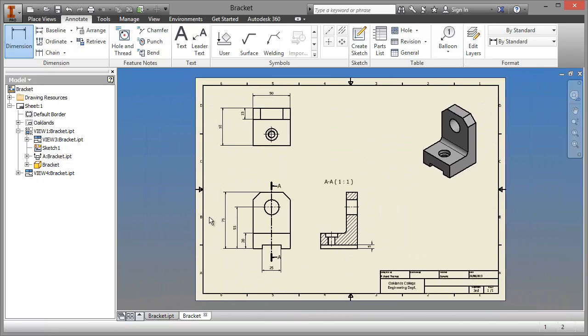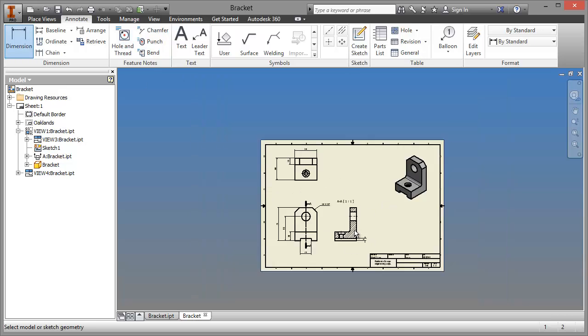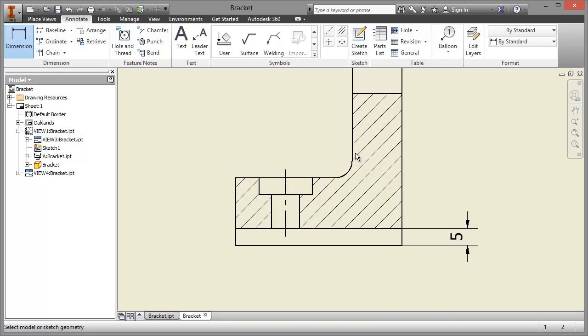Okay, so I think that's all the sizes done for the main bits. We'll just work through some of the more specialist type things now, things like holes and chamfers. Let's do chamfer first. Click on the angle and then a straight edge. So that's that one done. We've got another one, this fillet here, which we can use with the normal one. When you're dimensioning fillets, make sure that you don't pick any of the dots, you just get it on the red line.